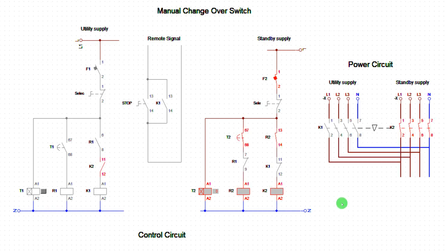When the transition is over, this one takes over. Now, when this one is working, standby is on, and the utility comes active, watch, it will take over. It will knock off this and take over. And once it takes over, this one will be knocked out. Now, when this one goes out, the genset will also shut down automatically.